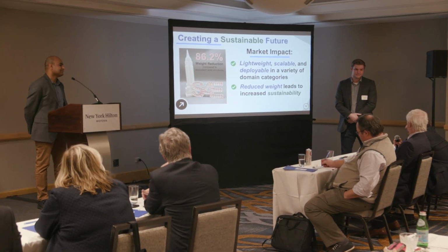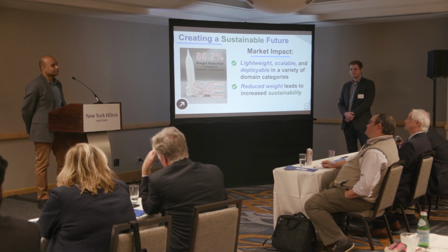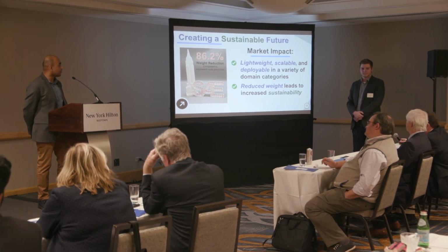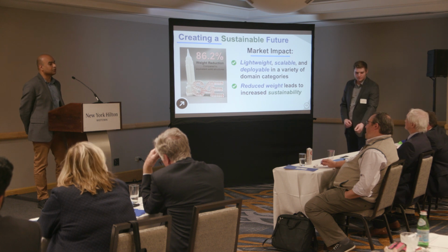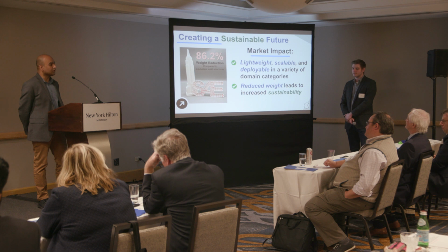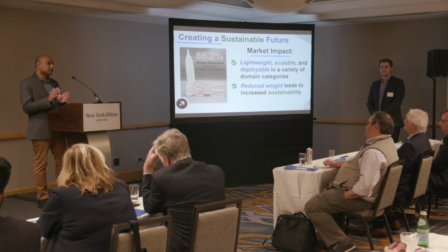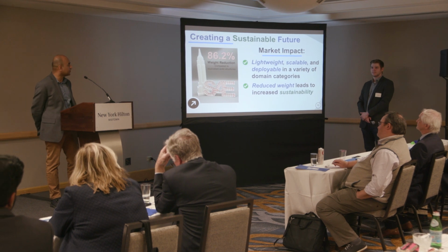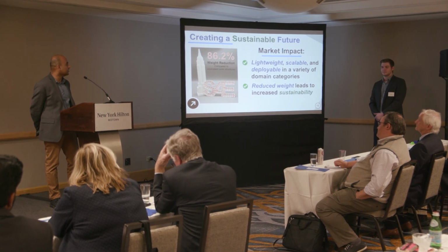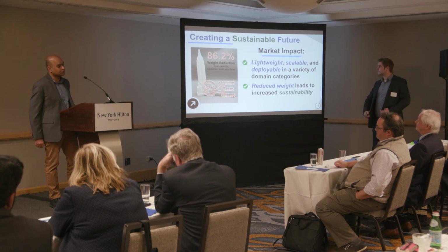Thanks. Is there any post-processing required after the parts come out of the 3D printer? No. And that is part of our focus, that we wanted to keep the manufacturing process as simple as possible so that we can fabricate complex shapes that do not require post-processing, so that we have an entire streamlined workflow for printing, right? So the trick there is making sure that the 3D printing process parameters are such that we end up with airtight filaments.